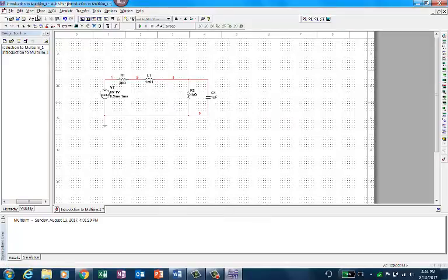What it means is that if you're running a simulation with high voltage and high current, say 1000 volts, 1000 amps, you don't need so much accuracy. You should be able to adjust the simulation accuracy so that it doesn't run into a convergence problem. That's a very common situation.